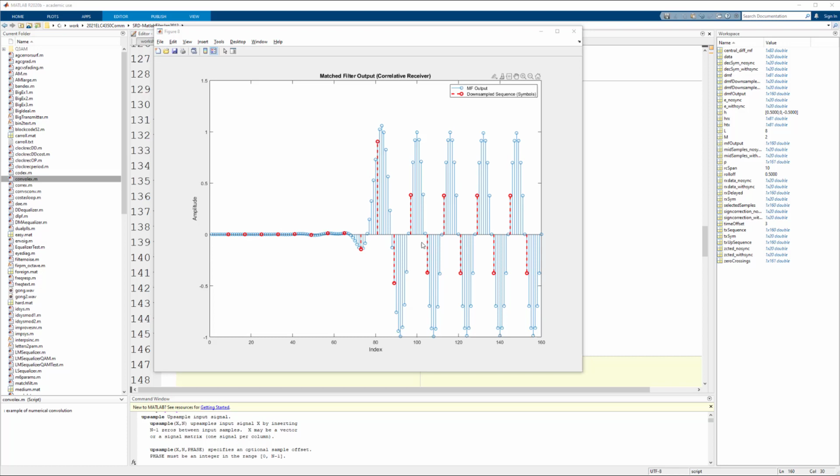So my thought is that if I take a derivative of this oversampled waveform, the derivative at those peaks should give me zeros. Those are the best positions for sampling. And if I input the derivative of this output to my timing error detector, a 0 stands for a locked position. That means I have a perfect timing offset.